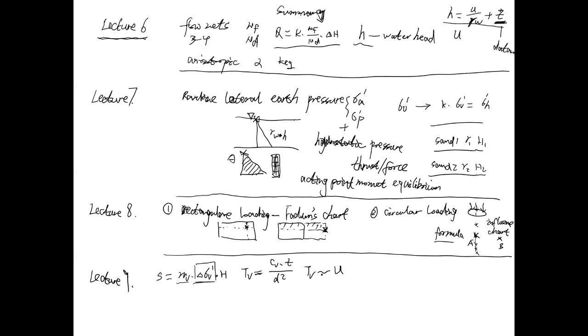You can find the relationship from the chart or from the formulas, for Uv. If you know Uv, then you know Tv, or if you know Tv, you know Uv. We have the corresponding formulas. You also need to remember the corresponding Tv value when U equals 50 or when U equals 90. That is very standard.